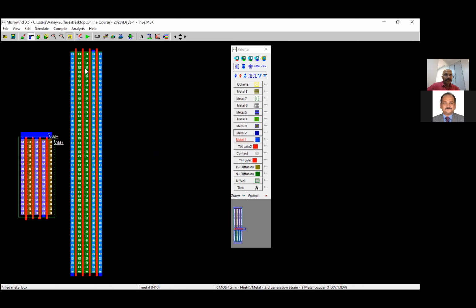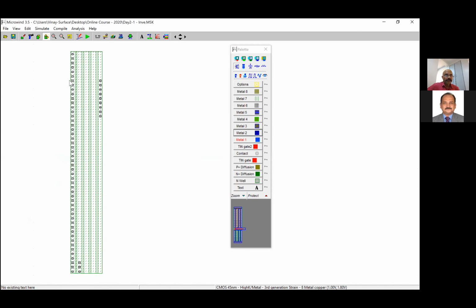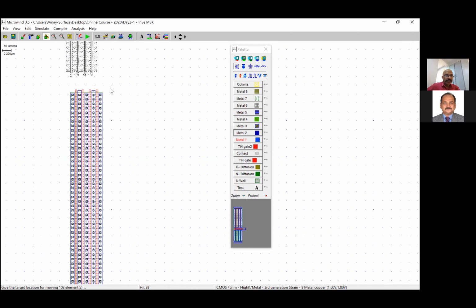So I made an NMOS that wide, which has around 17 milliampere of current, and I place the PMOS on top of it so that we can connect easily and redo the simulation.